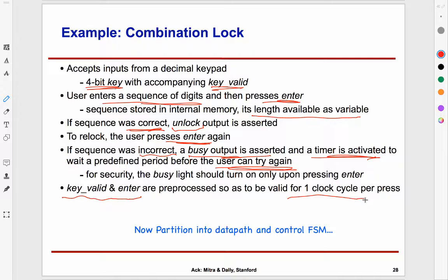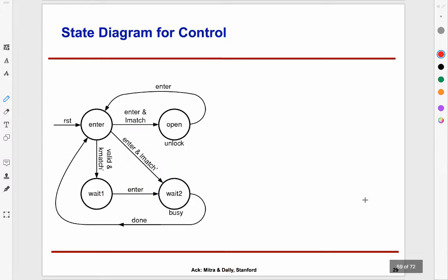So at this stage of the design, you basically will have to kind of mentally think in terms of, yep, I have a data path, I have a controller. What kind of operations do I need in the data path? What kind of signals are going to go into the data path? What kind of signals from the controller, vice versa? What are the external world signals? All those kind of things. So you'll have to kind of reason a little bit about that, and then come up with a high-level strategy. Okay. And that high-level strategy, again, remember I said assume that the data path exists. Let's first get the high-level state machine there.